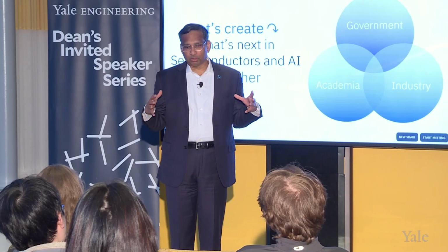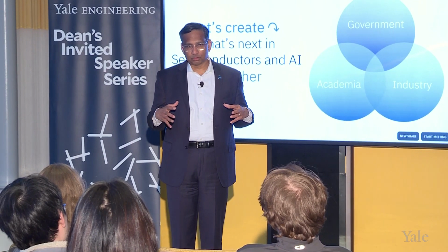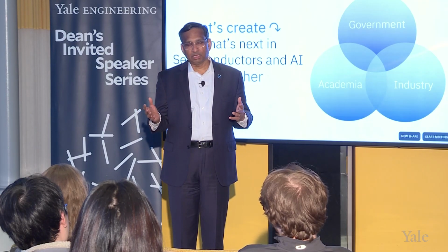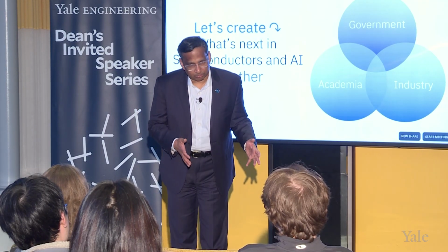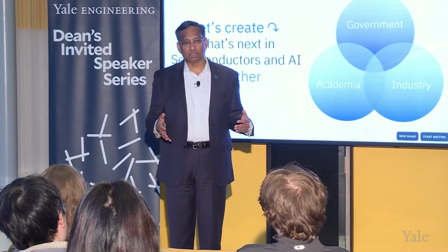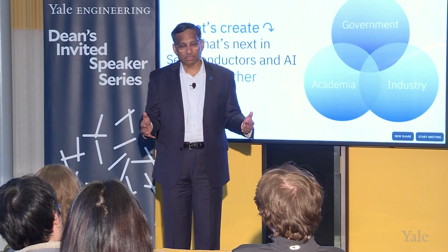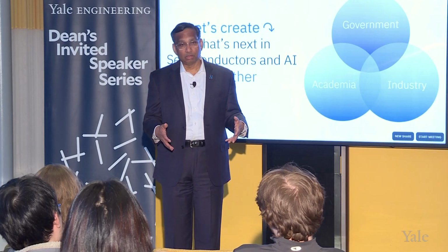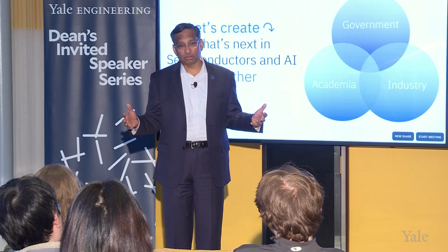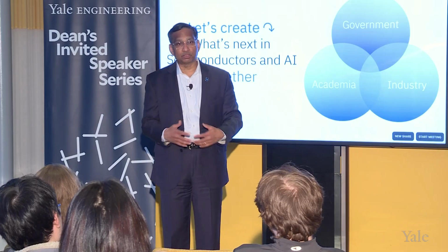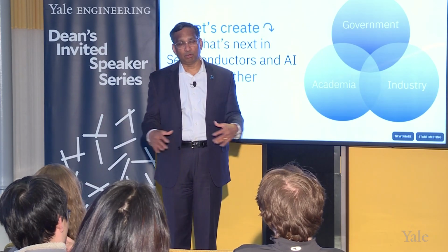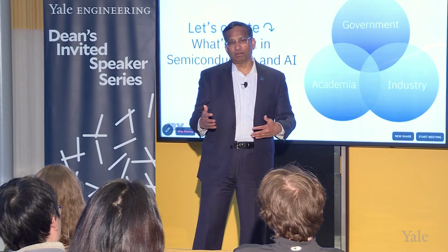What happens is if you put the memory on the chip itself to eliminate this movement of data from compute to memory, then there is a limit on how much memory you can put on the chip also. And that limits the size of model that you can then deploy in that particular application. Or if the model is big, then you have to use many chips to split that model across many different chips to be able to load that entire model. So I think that's the trade-off that we are studying.